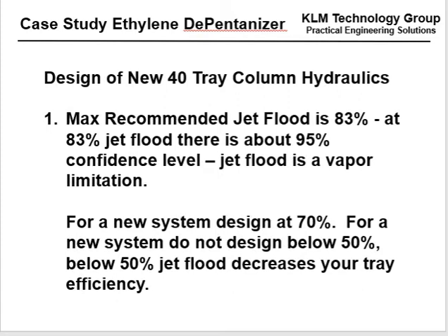Design of the new 40 tray hydraulics. So max recommended jet flood is about 83%. At 83% jet flood, there's about a 95% confidence level. The jet flood is a vapor limitation.